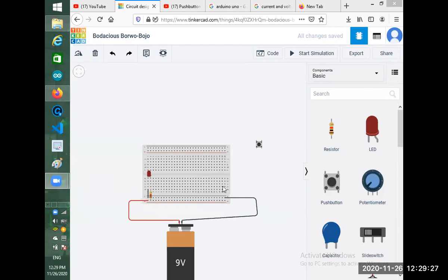We have this whiteboard. So how does this button look? It looks something like this. It has a wire here and a wire here, and a button here. Below this button there is a wire. When we push it, these two wires get connected, and at the same time these other two wires also get connected. So we connect this wire with our LED and connect the other with the positive terminal and the battery. When we push this button, only at that time our LED will be on.